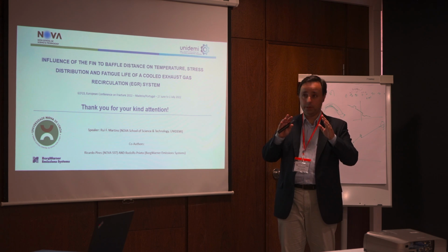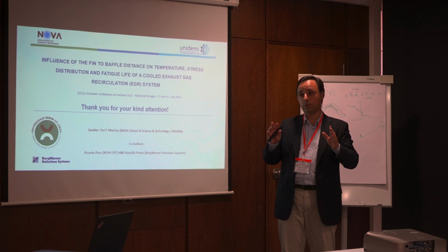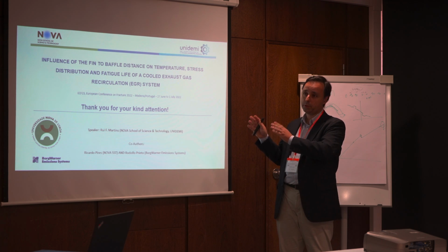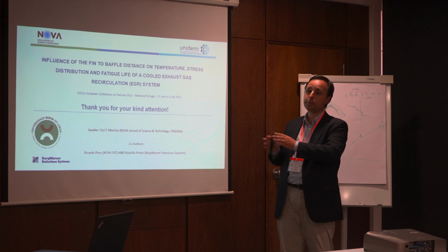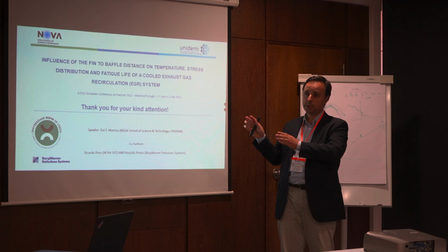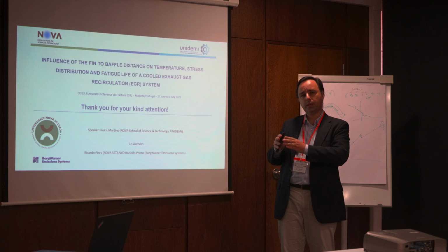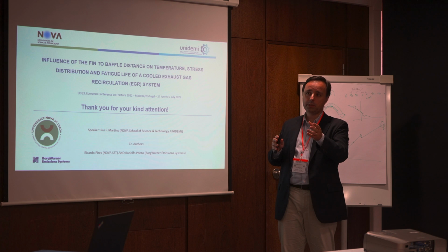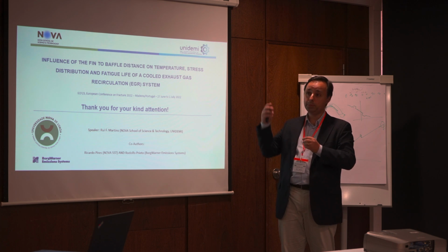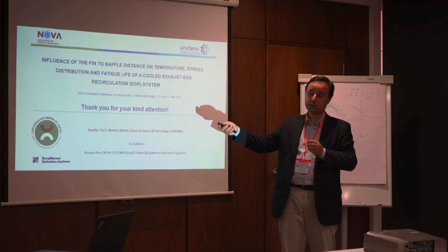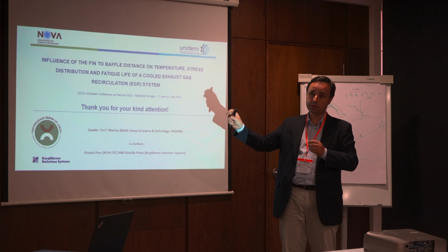But we do not have the strict values for the Coffin-Manson parameters adapted for the specific temperatures in the EGR. Probably, I do not remember now the temperature for those parameters, but I guess it's not the 600 degrees that we could be interested at the inlet of the EGR where the fins are more stressed.